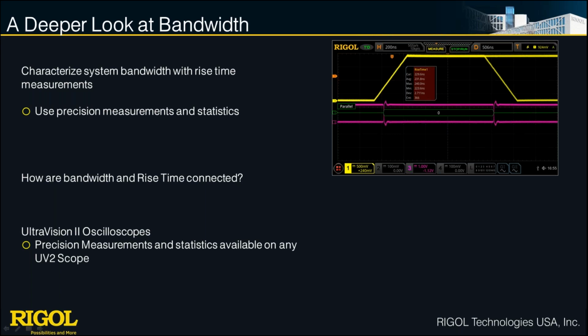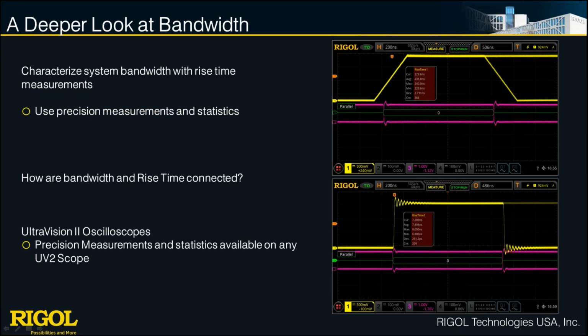So we can improve that by looking at our device and tweaking some of the bandwidth to improve the signal speed. And we can get that signal speed down, in this system, as far as about 8 nanoseconds, with a much higher speed transition. But that might cause us other problems too. So when we're thinking about this, as we change this sort of diagonal transition to a more vertical transition, how is this rise time connected to the bandwidth of the signal?